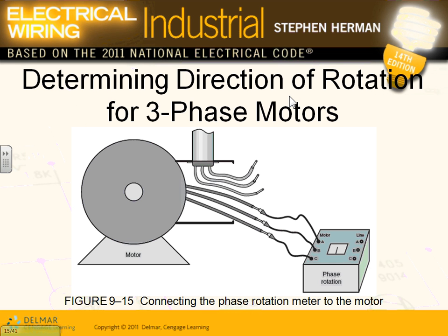So they have, smarter than Chad, a phase rotation indicator. The phase rotation indicator, right here. First of all, you zero it. You put it on zero before you do anything else. Then the motor is de-energized. I don't know how you do this in bigger motors, guys. I really don't. In smaller motors, you go to the rotor, Chris, right here, and you physically, mechanically rotate the rotor. So I want this rotor to go counterclockwise, right here. I want this motor to go counterclockwise.